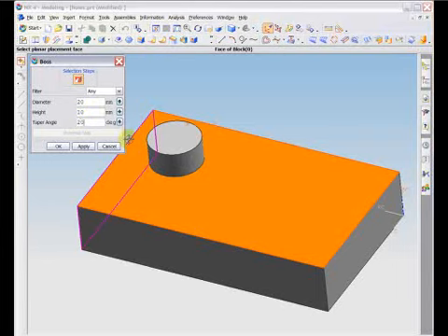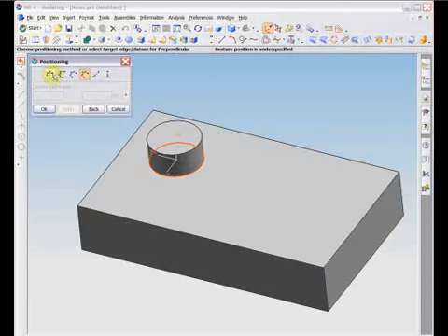A taper angle can also be specified, which will reduce or enlarge the angle of extrusion of the cylinder depending on whether it is positive or negative. If your boss was placed on a plane rather than a feature face, you may also choose reverse side, which reverses the temporary direction vector of the placement plane and thus the boss extrusion direction. The last step is to locate the boss with positioning options.